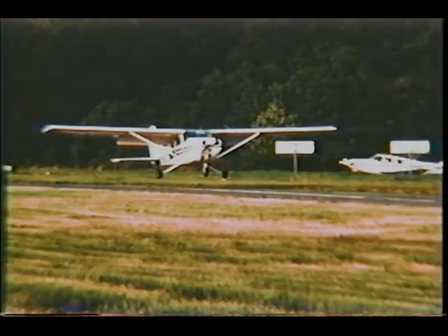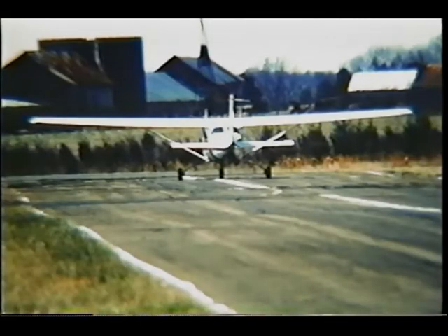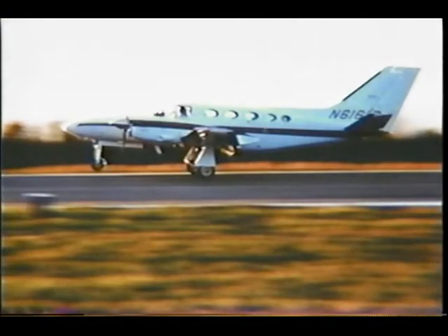However, did you know that if you fly a non-standard VASI, and that's the homemade variety, that even if you're flying the right airspeeds, you'd also better have a good idea of where the airport operator has located his aim point for you. You see, a displaced aim point could have you going off the end of the runway at the other end by suckering you into landing long. And since government publications do not provide specific information about non-standard VASIs, it's up to you to know what you're up against. And that completes our discussion of the 8 most common contributors to landing long.